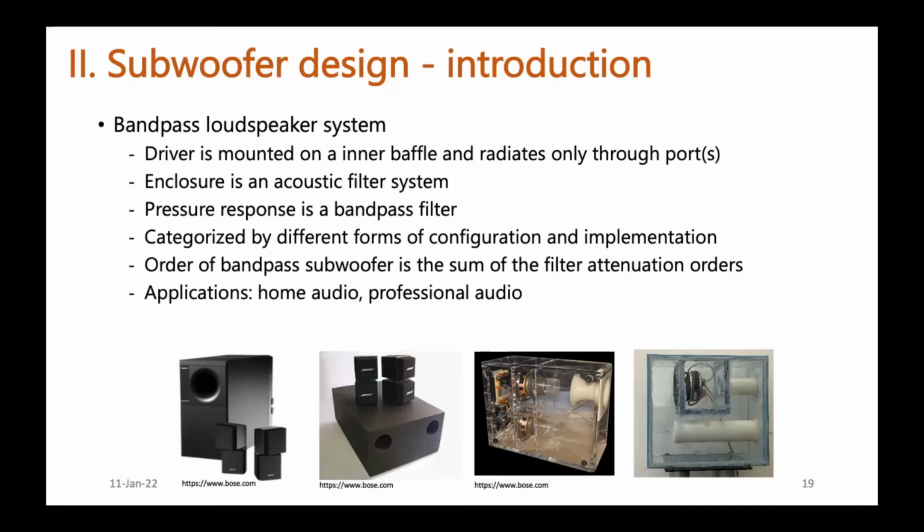The key feature of it is the driver does not radiate directly to the surrounding air, but is mounted on an inner baffle inside the enclosure. And the box only radiates through these ports. The enclosure can be regarded as a system of Helmholtz resonators, and its pressure response is of a bandpass shape. So it's called the bandpass loudspeaker.